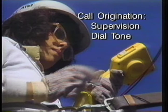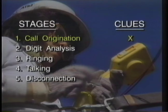If dial tone is disconnected when the first digit is dialed, you can assume that the problem is not occurring during call origination. Therefore, your investigation can proceed to the next call processing stage, digit analysis. Through this deductive process, a technician or any private eye can use the stages of call processing as a guide with which to isolate a problem situation. Inter-office call processing allows me to talk to my friend as easily as if she were right next door.